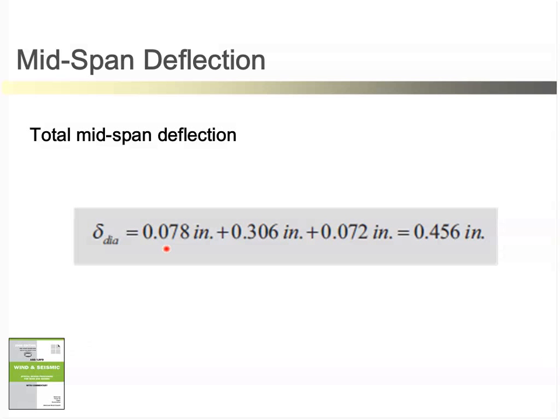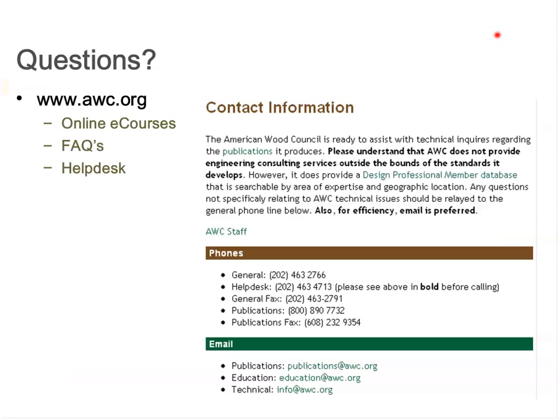The middle term is due to panel deformation and panel nail slip, and then the final term that we just calculated is due to the cord splice slip, to give us just shy of a ½ inch of deflection for that particular example. So that was a fairly quick look at the example as laid out and some of the assumptions.